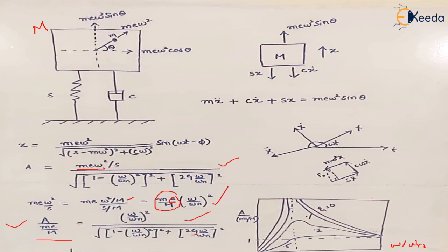So this is the kind of plot that we see, and in this graph we can see that at higher values of the frequency, so the values are increasing. So this is 1, right? So values are increasing in this direction. We can see that as the frequency ratio values are increasing, its amplitude is also reducing, and amplitude can be reduced by reducing what? If I want to reduce this value, we can reduce the mass and eccentricity of the rotating body. So for such systems, usually higher frequency ratios are preferred.